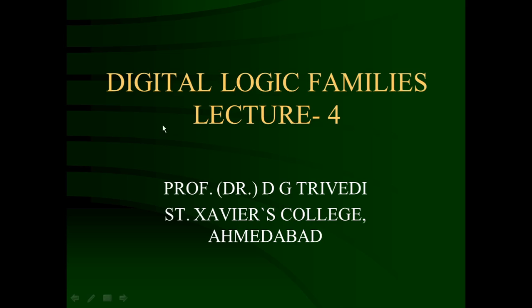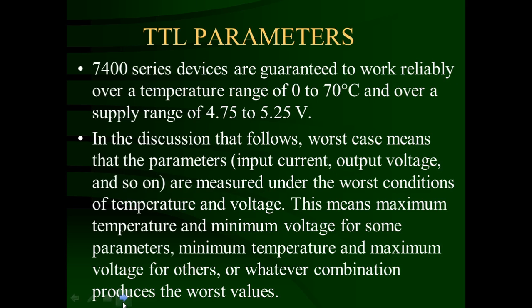Now this is the lecture number 4. TTL parameters. 7400 series devices are guaranteed to work reliably over a temperature range of 0 degree to 70 degrees Celsius and over a supply range of 4.75 volt to 5.25 volt.